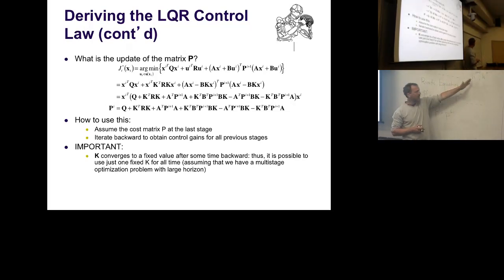The special gain schedule is truly optimal for this kind of finite time horizon problem. But given that it converges so quickly, it is totally sufficient to work only with the converged gain K. That essentially corresponds to an infinite horizon problem, where you assume you apply this forever after. The time horizon when it converges is usually about 50 time steps. It's very little, so after 50 time steps, the problem appears like an infinite horizon problem.